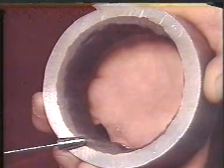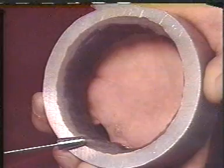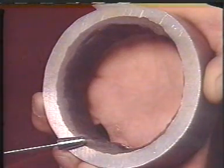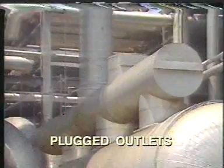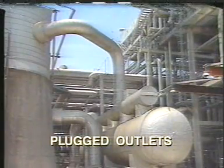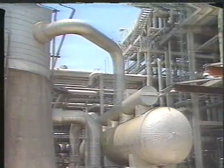Fouling or scaling is a common problem in furnaces, reboilers, and heat exchangers. As with a condenser, these deposits restrict flow through a vessel and reduce heat transfer efficiency. Solid deposits can collect and plug screens, valves, and pipes that serve as outlets from a distillation column. Plugged outlets seriously restrict the amount of product that can be drawn from a tower, and they must be cleared if the column is to operate normally.